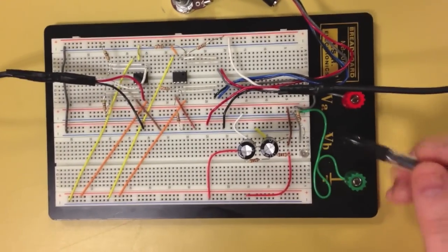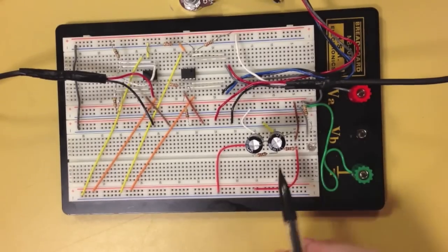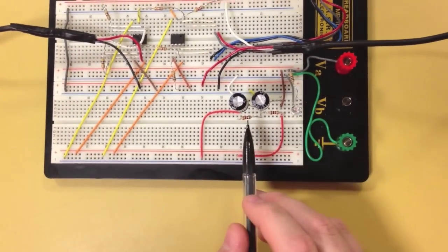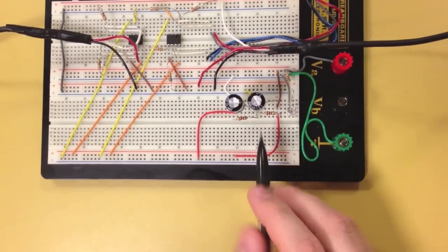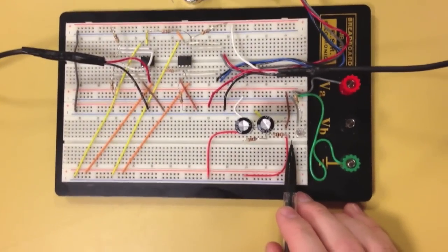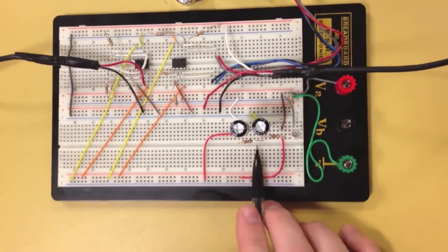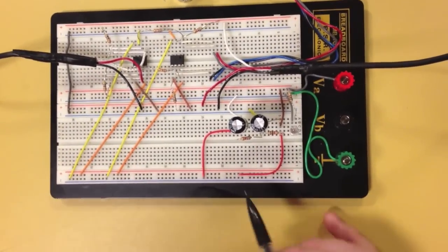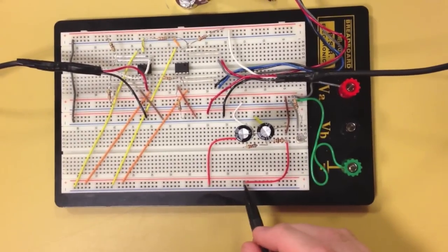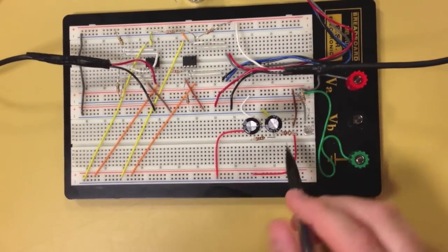Essentially, it takes positive 18 volts from here, runs it through this first resistor, runs it through the second resistor. Each resistor drops 9 volts off of the power. So if you measure from the middle to here, you have plus 9 volts. If you measure from here to here, you get negative 9 volts, as long as you use this as your reference. So as long as you connect this side to your positive rail and this side to your negative rail, you can generate a split rail voltage reference to here.